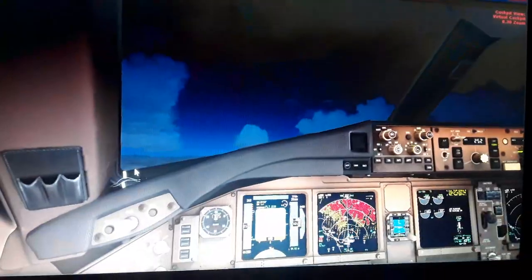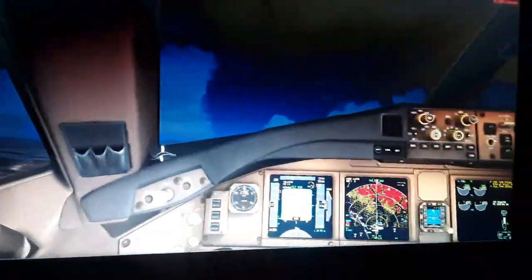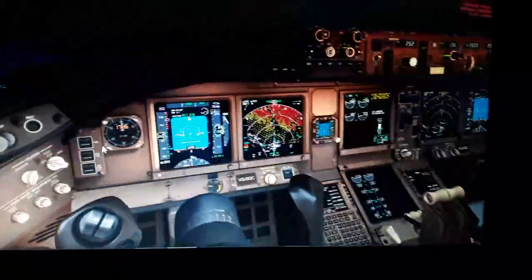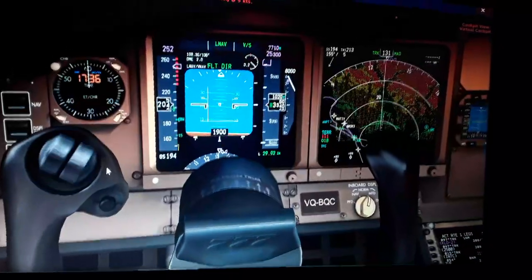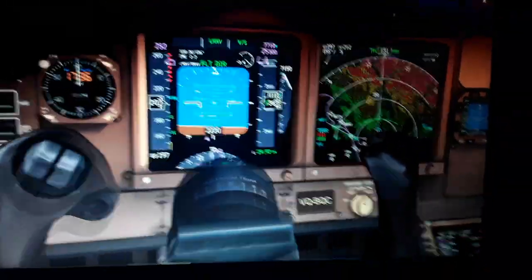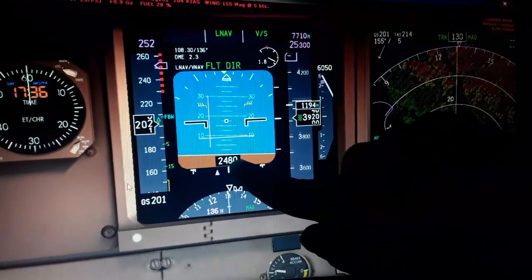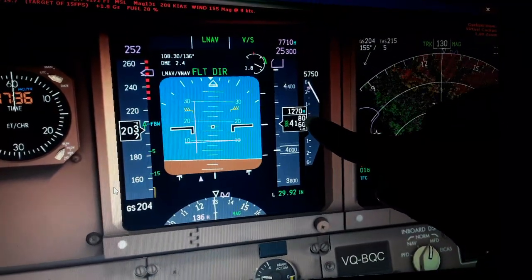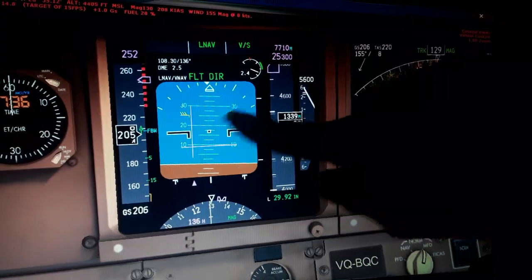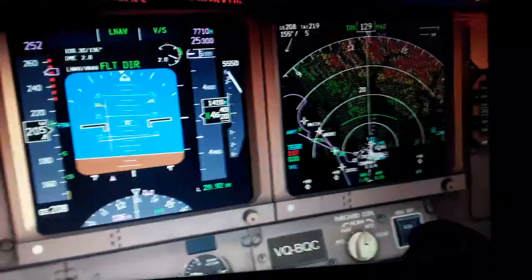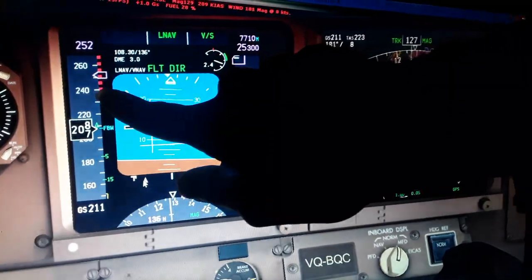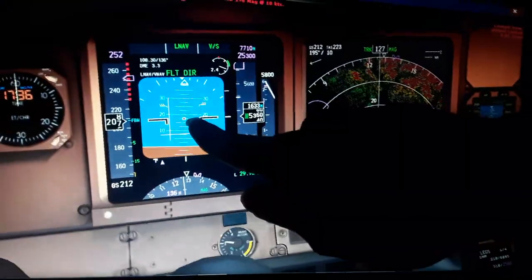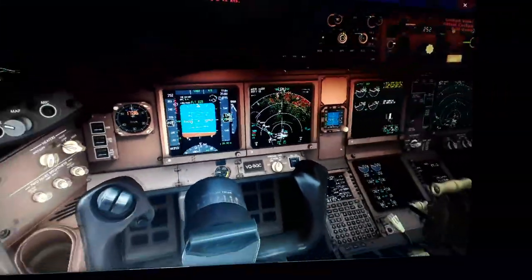So you see as we depart, and we have 16 more minutes left for this, so I'll give you 20. So we need to pitch up a little bit the aircraft. So you can see we are 2,400 feet above the ground level, but 4,100 above the sea level. We climb with 5,000 feet per minute. The airspeed is 220 knots right now. The stall speed is here, the flaps limit, the pitch attitude of the aircraft about 17 degrees, and the flight plan.